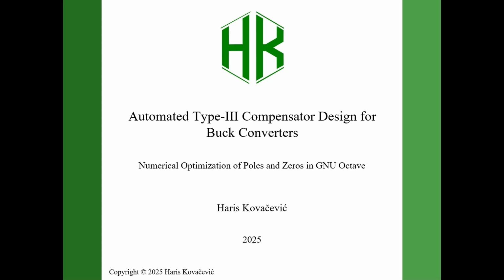Designing a Type 3 compensator is usually taught as a manual process. Place a pole here, a zero there, simulate, adjust, repeat. In this video, I want to show you a different approach. Instead of manually tuning poles and zeros, we let an automated script design the compensator for us, based on a desired crossover frequency and phase margin.